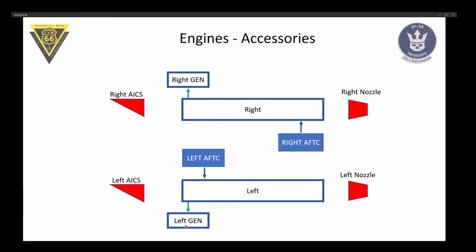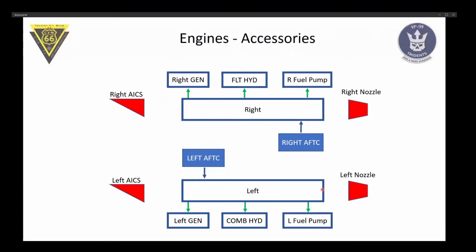Then you have the left and right generators, which are mechanically driven by the accessory gearbox, and they provide the electrical power. Then we have hydraulic pumps. The left one powers the combined hydraulic system, and the right one the flight hydraulic. We're going to talk about that later too. And each engine has its own engine-driven fuel pump.